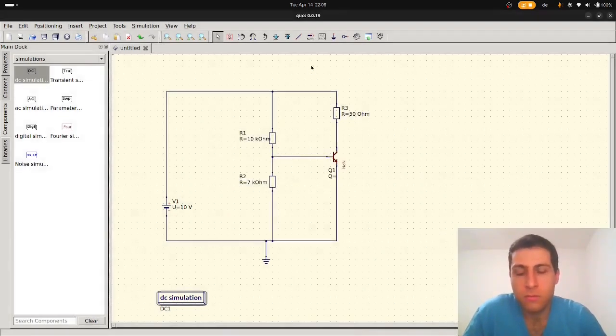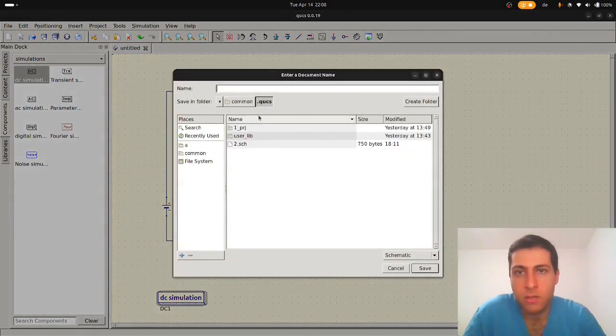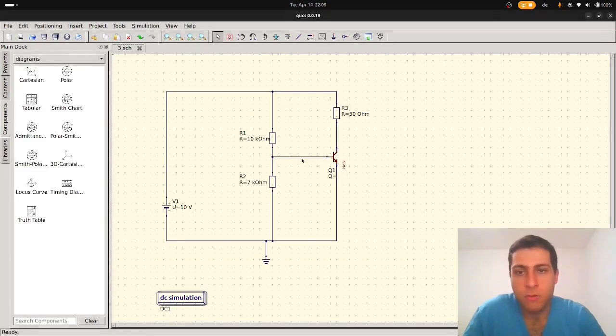Okay, so I'm gonna say calculate the DC bias, and at first it prompts me to save my project simulation, and then I'm gonna say simulate again.